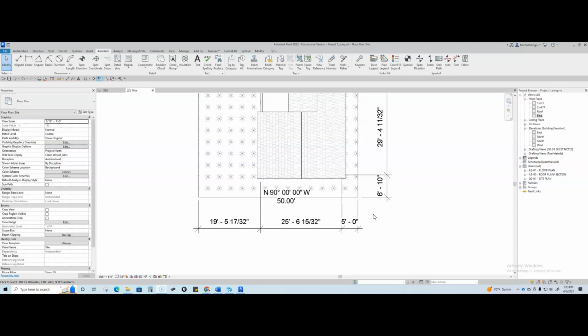So depending on your property, you have to go to the zoning map at the city. Usually they're all available online. Determine what kind of zone you fall into, whether it's an R1, R2, R3 or whatever designation they have in each city. And they should have setback requirements for the type of zone that your property's in.